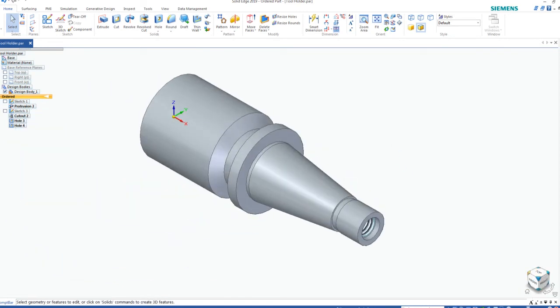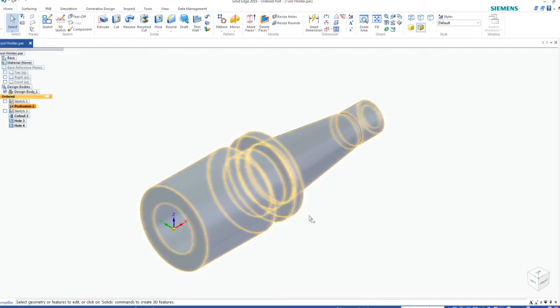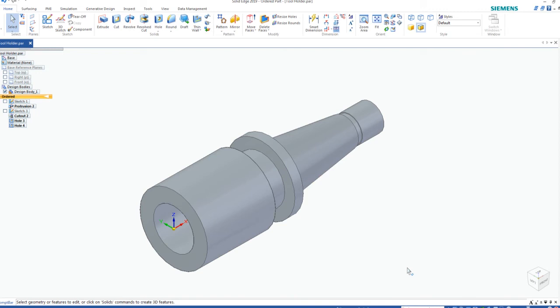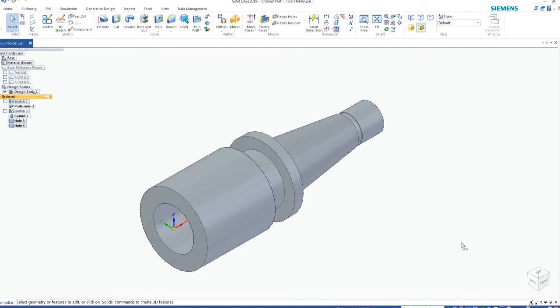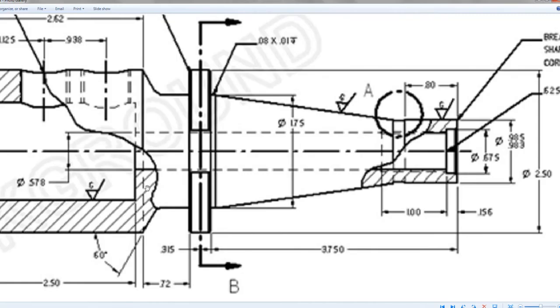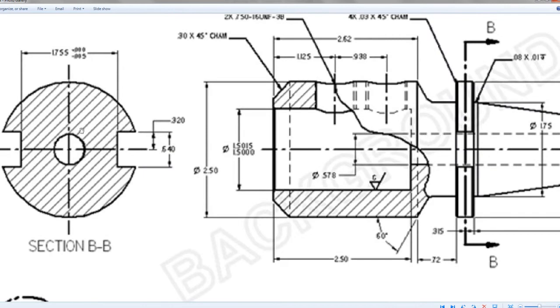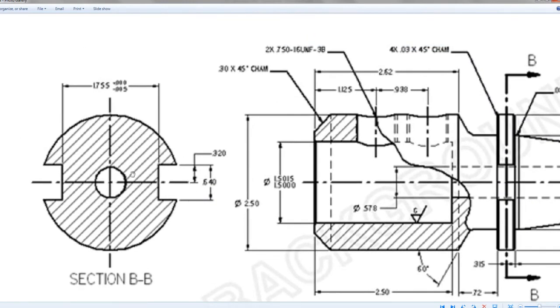All right, so our next step is there are a couple of key tabs on this flange right here, and it's shown on our section view. So if we take a look at our section view, there it is. There are a couple of key tabs, and once again, we have an overall opening. It's indicating where it's going to be. Here it's also giving you a dimension to indicate where it is from the center. What we're going to do on the modeling end of it is use one of the relationship tools to center the cutter tool.